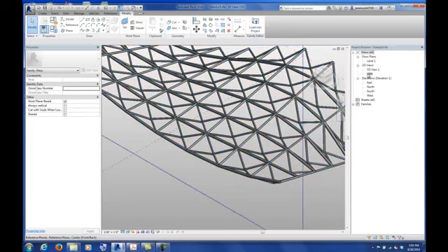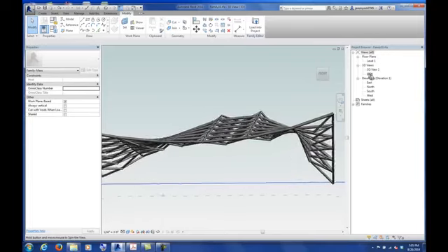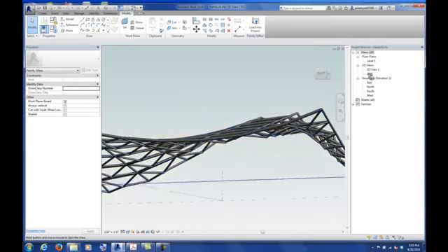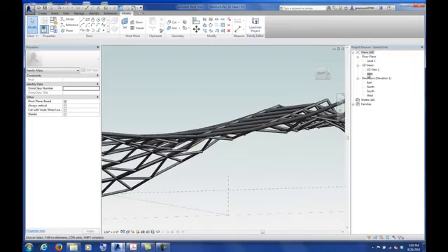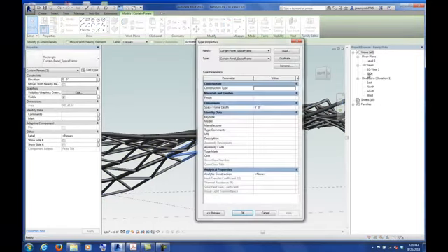Now another question I had was, some of you applied your space frame. By the way, I could also do the same thing, and I'm not going to do it right now because I want to move on. But you notice my space frame, the depth of the curtain panel, might want that to be a little bit deeper, like 8 feet, just for now. I could also make that space frame depth some kind of formula. Remember, that's a thing that we can manually change.